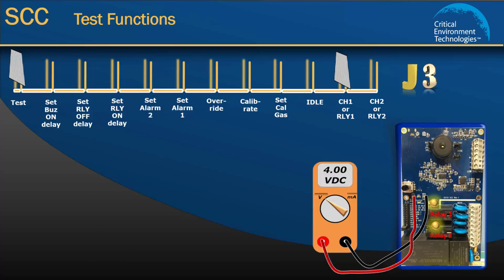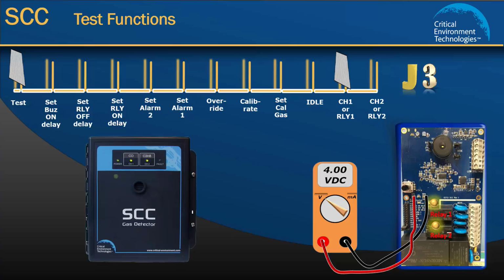Watch the LED lights on the front of the enclosure as they cycle their test functions, and make sure they all turn on and channel 1 and channel 2 show both green and red lights. To test relay 1, turn the rotary encoder dial clockwise slowly until relay 1 produces an audible click. The test points will output 3 volts and the relay 1 LED light on the board will turn off.